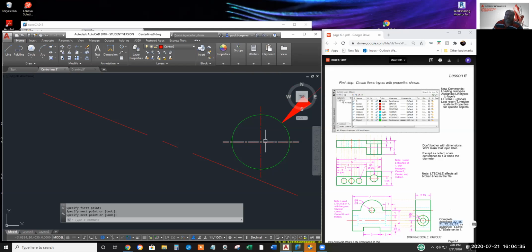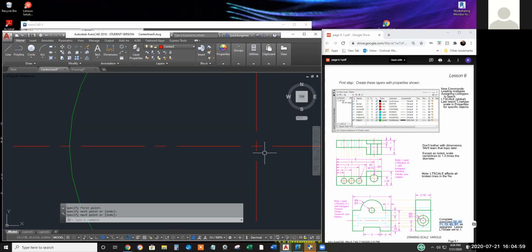I'm tempted to say if you got a single plus sign in your center lines for a hole in model space, I think it'll show a single plus sign in your huge circle through a viewport. No, it changes based on the scale of the viewport. If the viewport was 1-to-1, then it would be the same. But as the viewport changes, the line type actually scales with it.